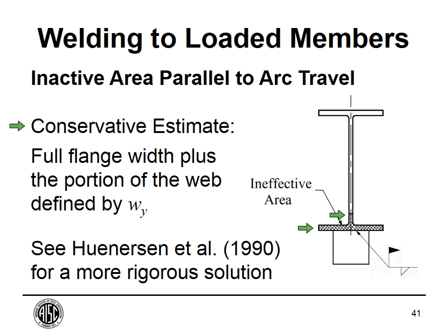Hopefully we'll remove some of the load before we weld it. So we're going to have a smaller load applied, hopefully, and then you can locate these plates that are transverse to the stress at a location along the length of the beam where the moment is much smaller.